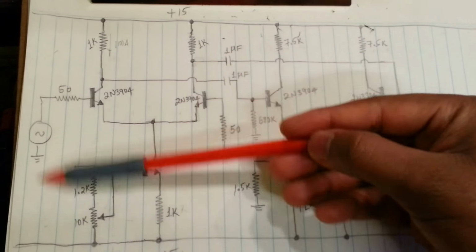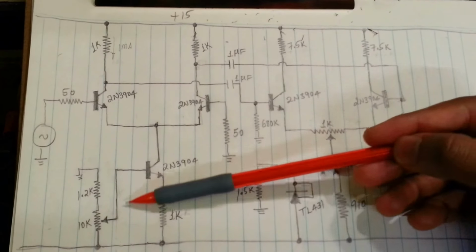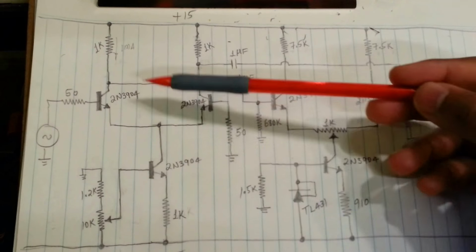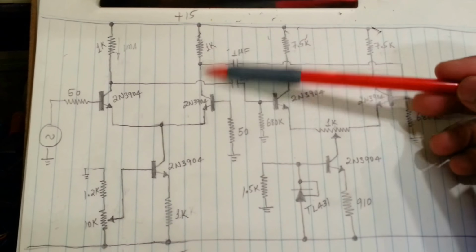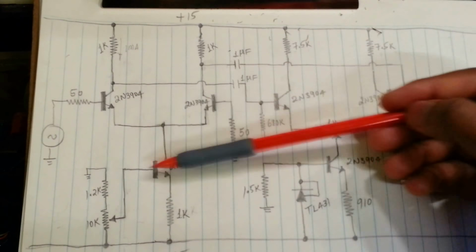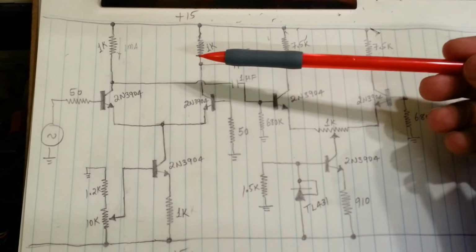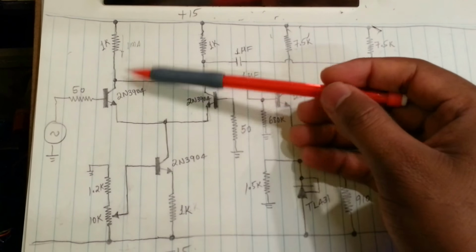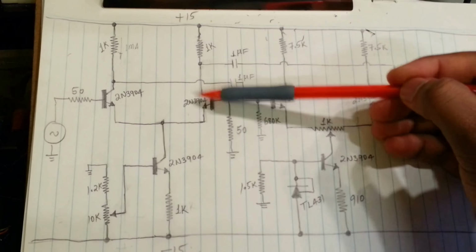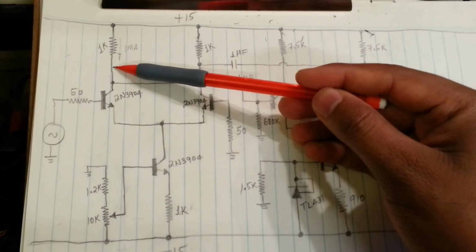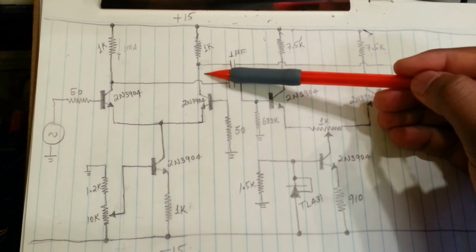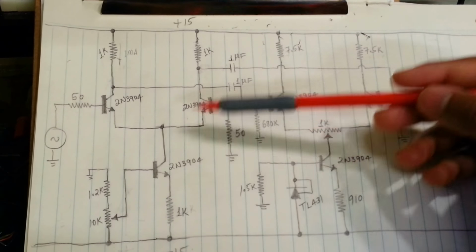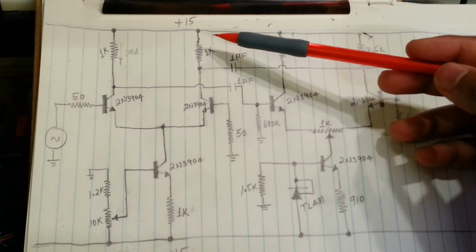Basically we have a first stage differential amplifier which will be able to control the current source here, thereby modifying the quiescent current that flows through these two transistors, which will modify the gain of the amplifier. And when we modify the current in these two branches, the drop here, which is the collector voltage of these two transistors, will shift up or down depending on how we change this current. That will cause an undesirable effect,